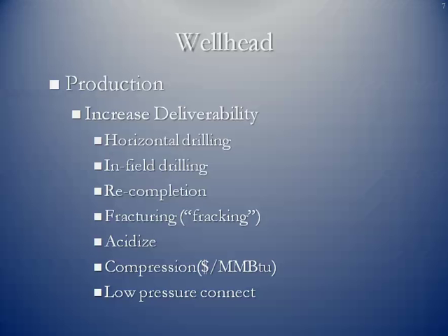Wells that start to decline, there can be a recompletion. Now, that can be two different things. A recompletion can be where you go down in and you attempt to do something additional to the existing reservoir, or you find another reservoir, another layer, another producing zone, and you go back down and you complete that.